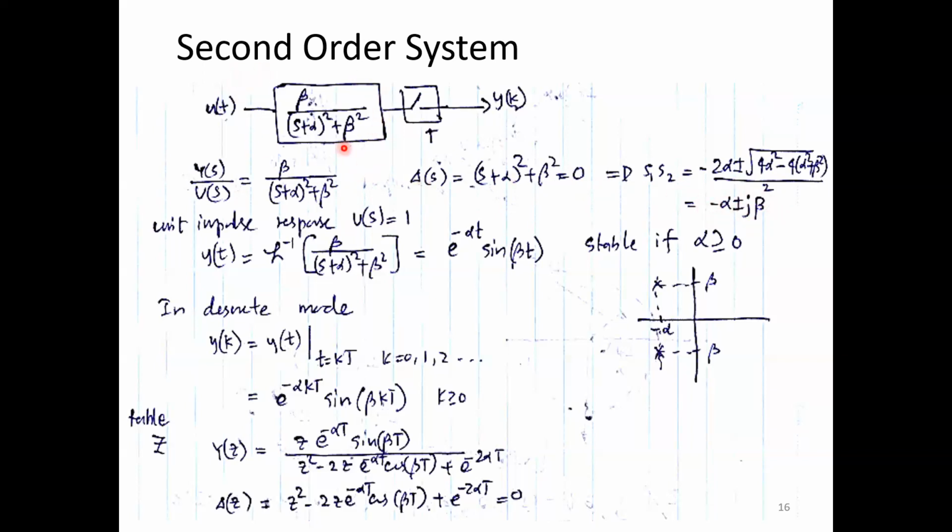So why we write the transfer function in this format in the first place is that you can clearly see what comes with s is the real part of the pole, and what comes here as plus beta squared, the beta is the imaginary part. Okay. So even without doing any of these things, a conversant person could tell me alpha is the real part, beta is the imaginary part. So the poles are alpha plus j beta, alpha minus j beta. Okay, a negative alpha rather.